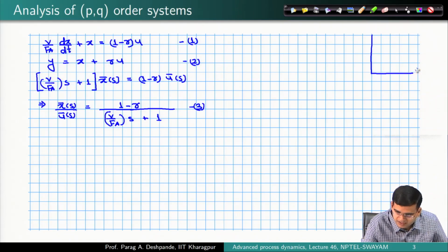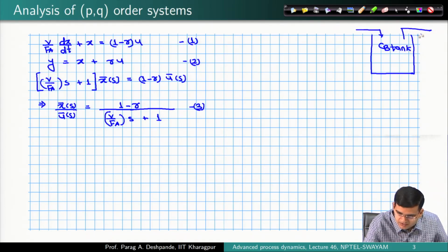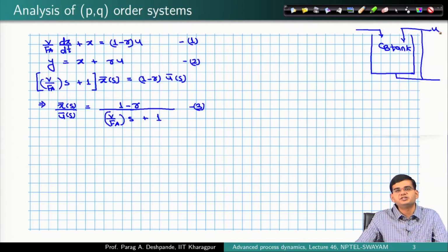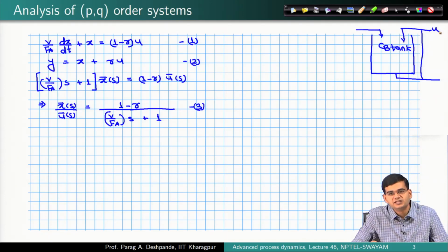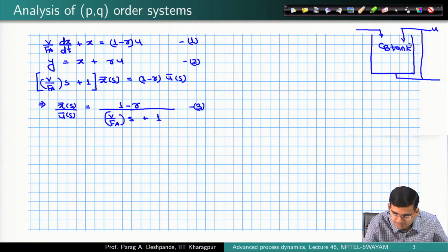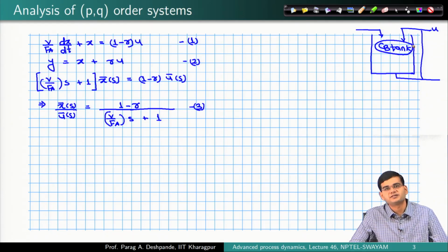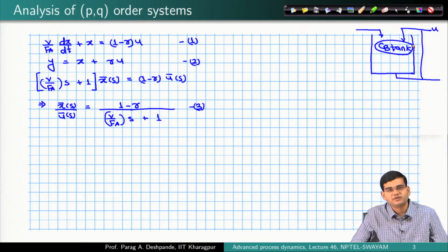So, you have here C B tank, right. So, as you change the variables of u, which involves C B feed, F B upon F A, how does C B tank change? What is the response of C B tank? This is what this transfer function gives us.